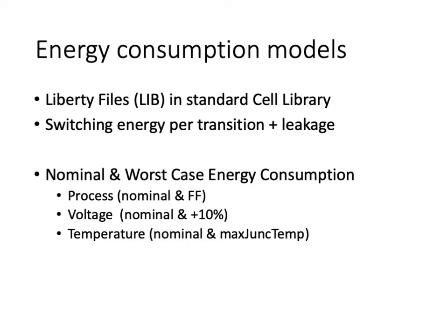After the low-level definition of the design is obtained, each of the low-level gates, for instance the NAND gates, NOR gates, AND gates, OR gates, are then mapped to specific gate level designs, that is transistor level designs of gates that can be manufactured by a fab.